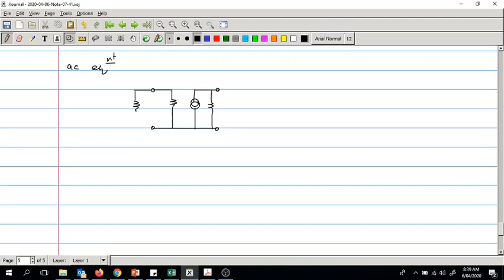Beyond the transistor, on the left hand side you have these two resistors. Let's label this as RB1, where RB1 is R1 parallel R2. Then we have the RS and VS. Okay, now what next? We have this R pi.